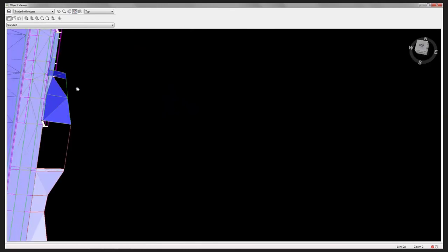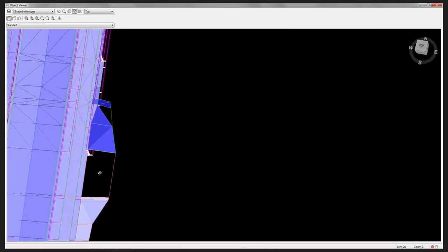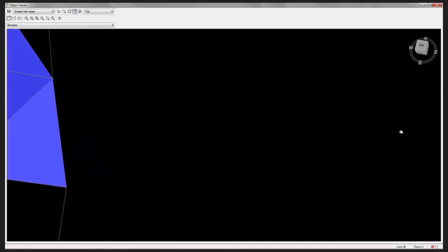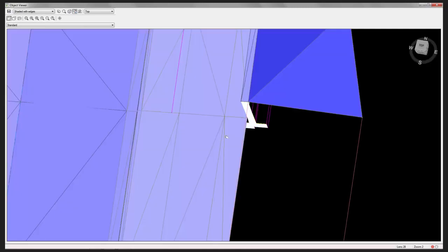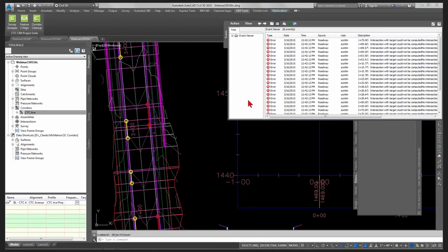I can see here I had just a standard fill or cut, and I can see right here, get this over, there's my wall. So at this point right here, I exceeded the 4-foot cut, so it started putting in a retaining wall. Here, I was at 3.95 feet cut, so it did not put that in. But it gave me the ability to put in a retaining wall whether or not I needed one. So quick design.